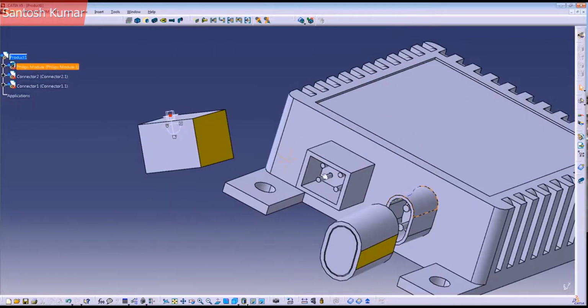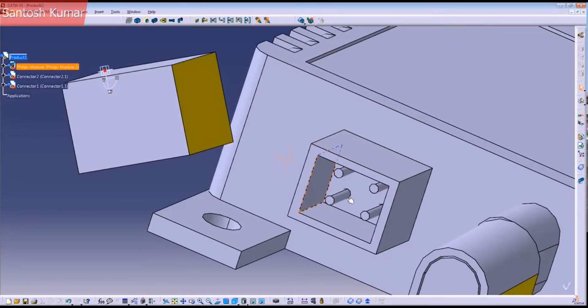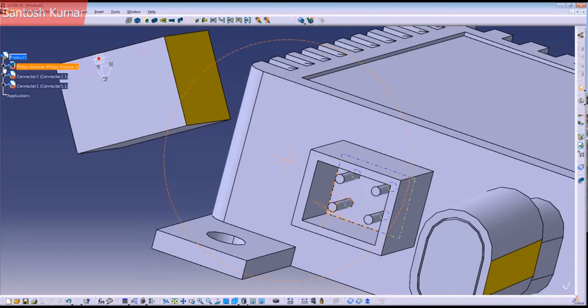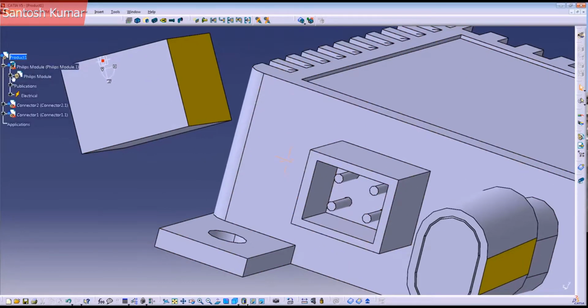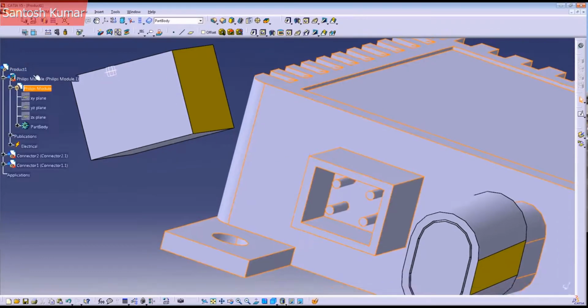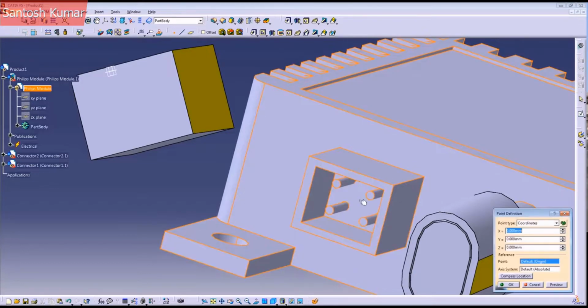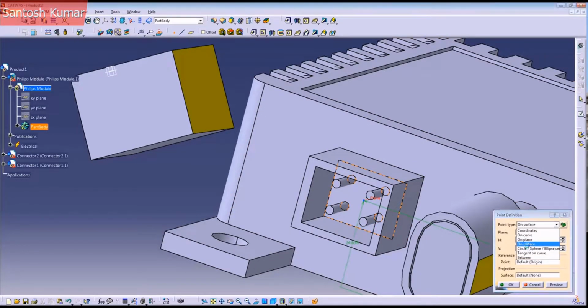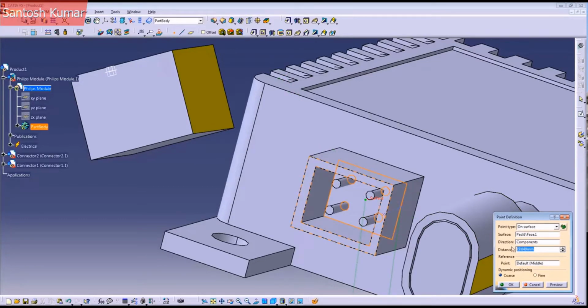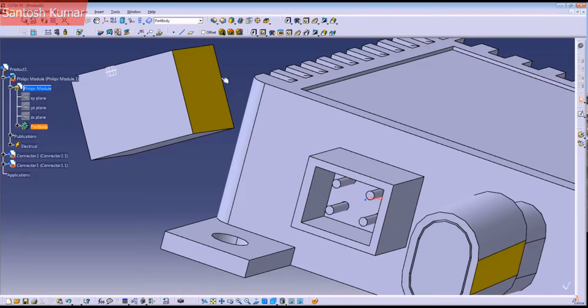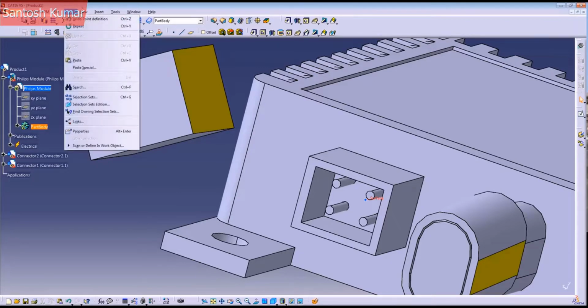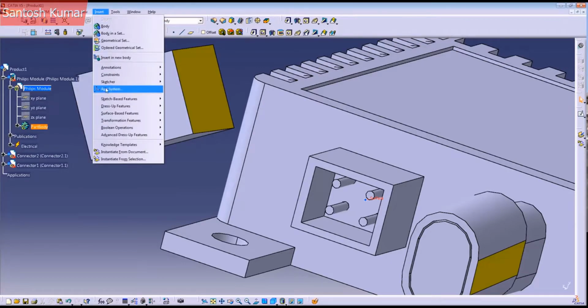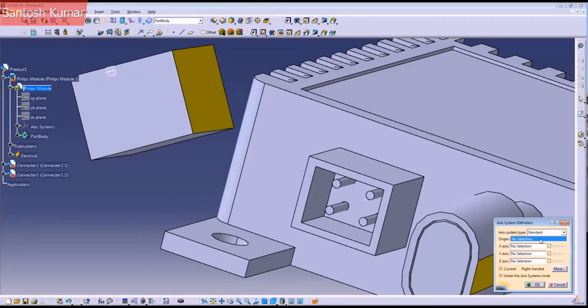And let's define another cavity for this one, but for this one we're gonna create it differently. So let's create a middle point here because we're going to create an axis. Just let me create a point. Just put here surface and just put 0 millimeters just to have the middle point. Press OK. And after that, let's go to create an axis system.